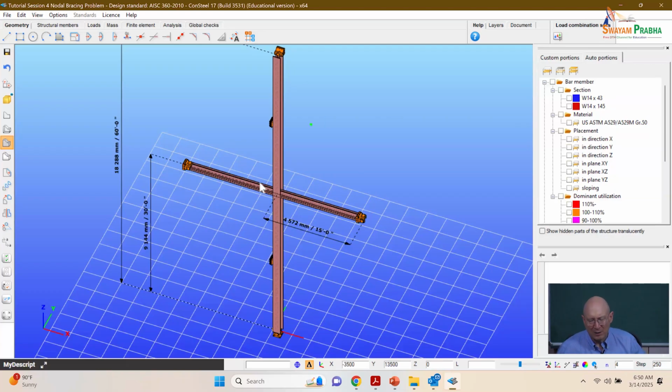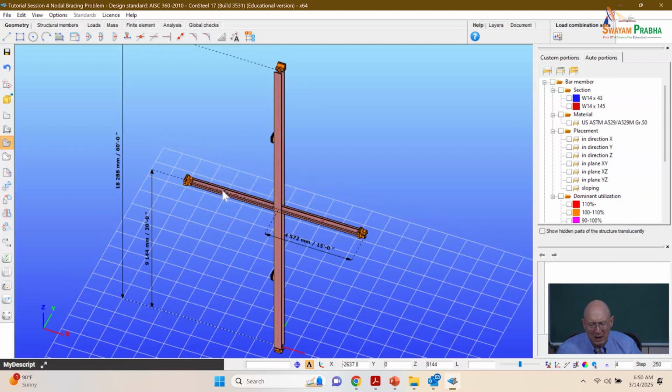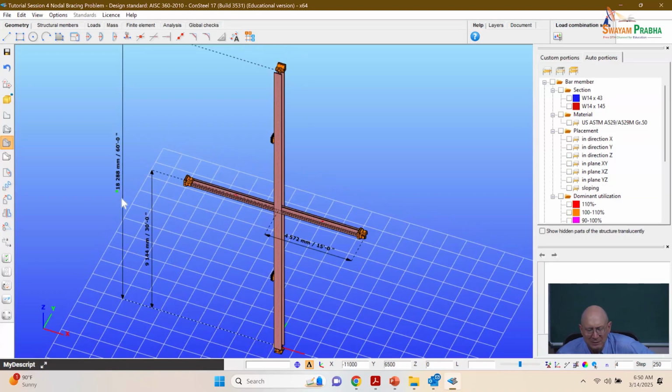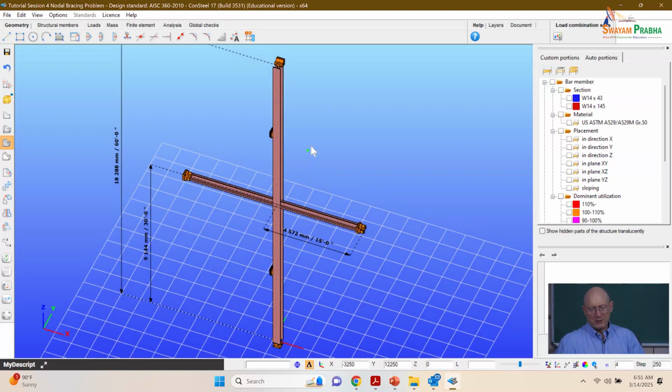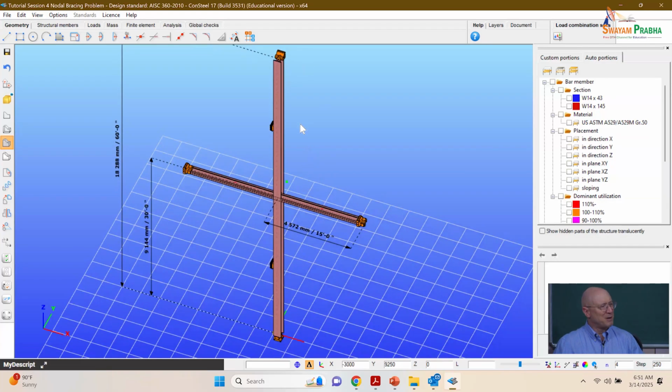The column needs to span from top to bottom, 18.288 meters or 60 feet. It could be a boiler that we're supporting in there, or some kind of shaft that's an opening that we can't put framing into. So that column has to span that entire height, but we can brace it at the top and the bottom. Okay?